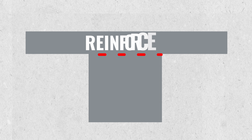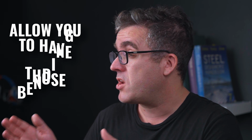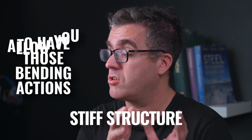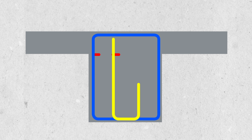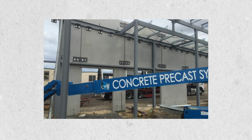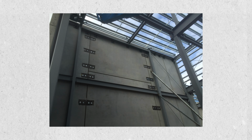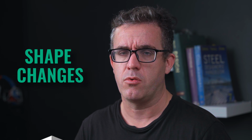So if you have a weaker plane, potentially you need to reinforce through those joints to stop those transverse shear actions from occurring. There's an interaction here that allows you to have those bending actions and have as stiff a structure as possible. You need to make sure those planes sliding on top of each other have enough strength or reinforcement through them. Most of the time this is not so critical, as with things like concrete or structures that are solidly built together, you don't need to worry so much. This is unless, of course, the shape changes through the height of the structure.